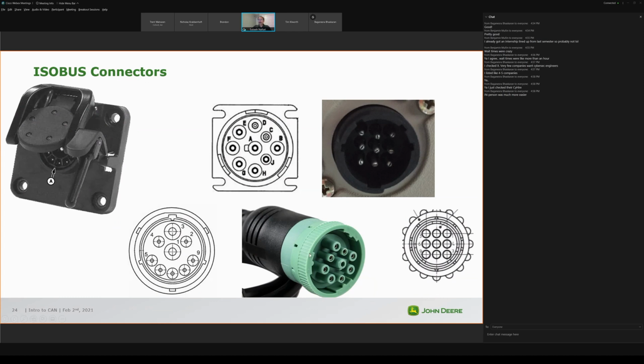And then you have a diagnostics connector. This could be in the cab or on the implement itself. This is a standard again. It supports 2 CANs and a power supply, so that the connecting device, which is for diagnostics or programming, can talk to the controllers and program them or diagnose them. And this is an ISO aux connector, we call it the aux connector.